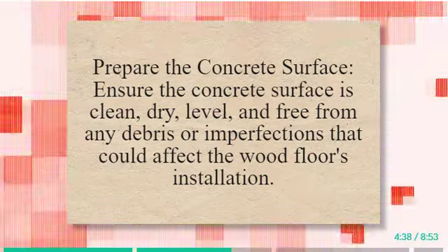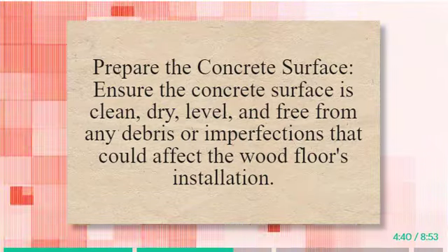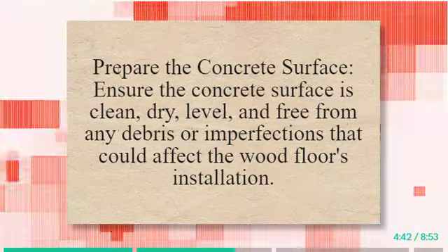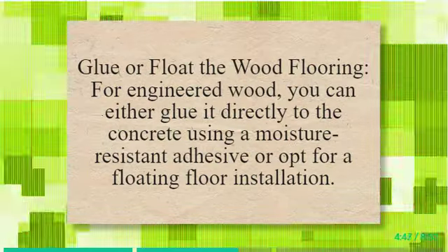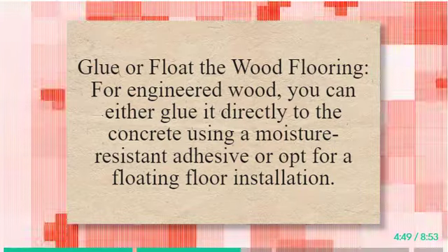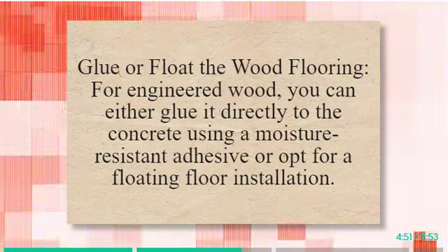4. Prepare the concrete surface. Ensure the concrete surface is clean, dry, level, and free from any debris or imperfections that could affect the wood floor's installation. Use a leveling compound or grinding machine to create a smooth and even surface for the wood flooring.